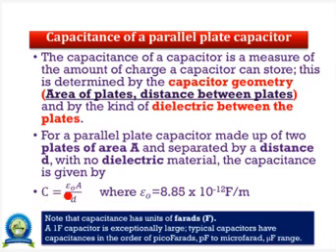And there is an inverse relationship between capacitance and the distance separating the plates. So if in this case I assume that my epsilon naught is constant and A is constant, then I can say C is inversely proportional to D. And the implication here is this: when the value of D increases, the capacitance of the capacitor will decrease because there is an inverse relationship between them.